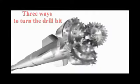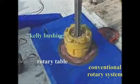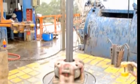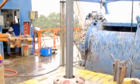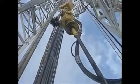What causes the drill bit to turn? There are 3 ways to turn the drill bit. The first is the conventional rotating system using the rotary table, the Kelly bushing and Kelly. The Kelly is a square or hexagonal shaped 40-foot length of pipe that threads into the drill pipe. A swivel connects the Kelly to the hook.